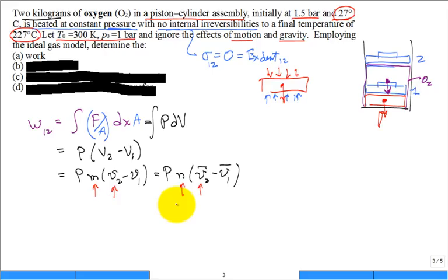The amount. Instead of mass, it's amount. And what is this v bar? No, it's not the average. Some classes we use the bar for the average. But what is the v bar? It's not per kilogram. It's the volume per amount, meter cubed per kilomole. Are you joking me, Professor? No, I'm not joking you. We can work this problem in the mass perspective or amount perspective.